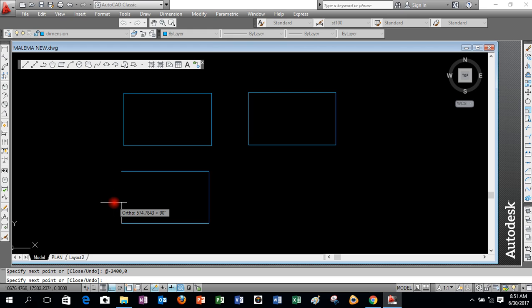So you have that, and now you can just close it instead of maybe putting at 0 comma 1400. You just say close. In this case, you type C and then you press enter. In that case, you have closed the diagram. So you can see that this is a rectangle. We've drawn a rectangle using the line method.